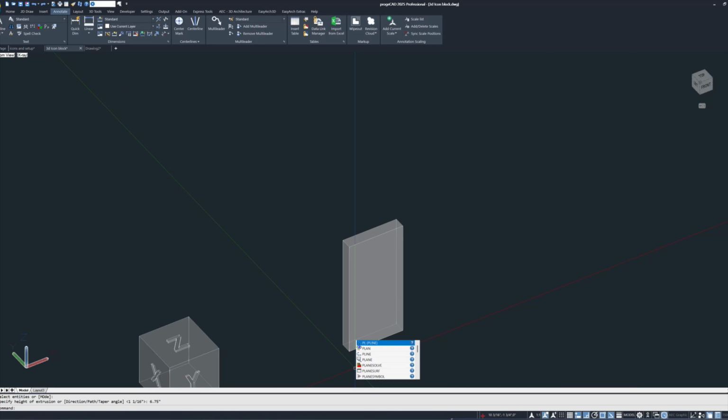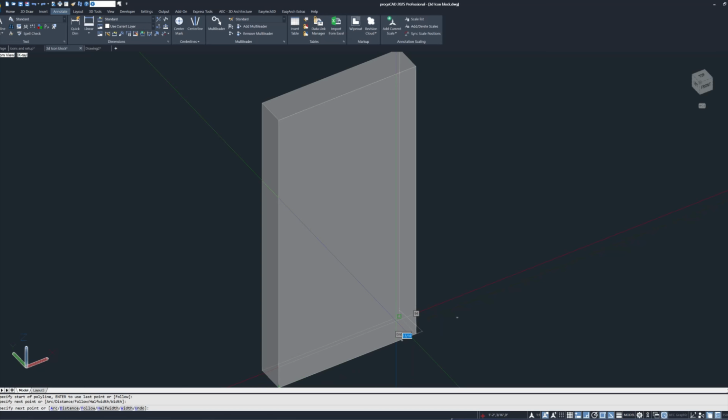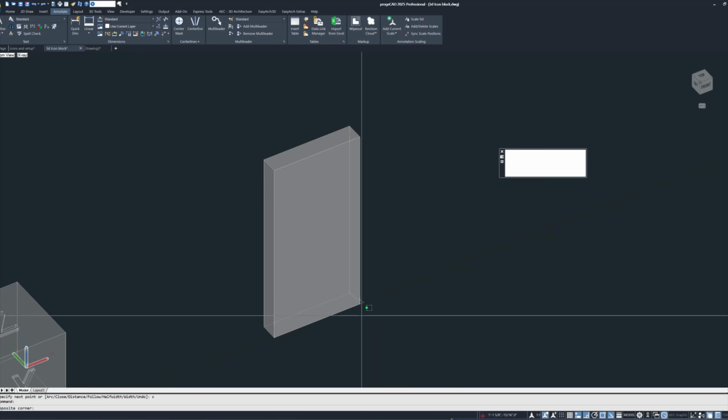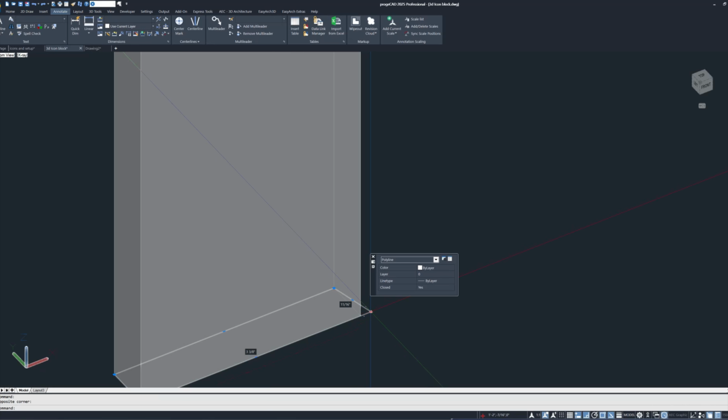Our next task is to define the thickness of the box and to draw another polyline so we can use this as the phone case. Once a user gains skill to plan, the next steps will be beneficial to the steps we use now. To define case thickness, it is best to sketch out a polyline to the interior space, then we can simply offset the required thickness. From here, enter the desired thickness of your case and make sure that only the polyline is selected, then enter a desired distance.